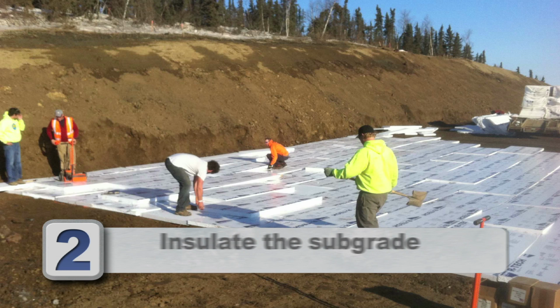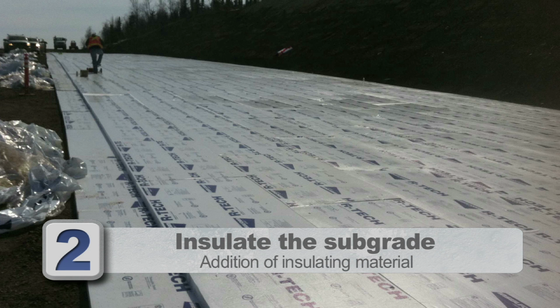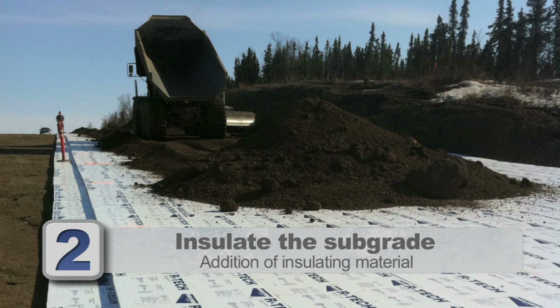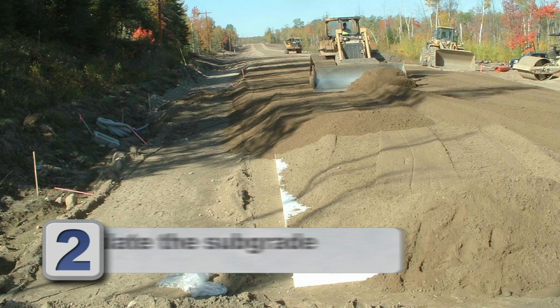The second method is to insulate a frost-susceptible subgrade from the upper pavement layers to inhibit the top-down advance of frost. This can be done by placing a layer of insulation 18 to 48 inches below the roadway surface. This depth is needed to prevent variable icing on the surfaces of adjacent pavement sections with different underlying structures.